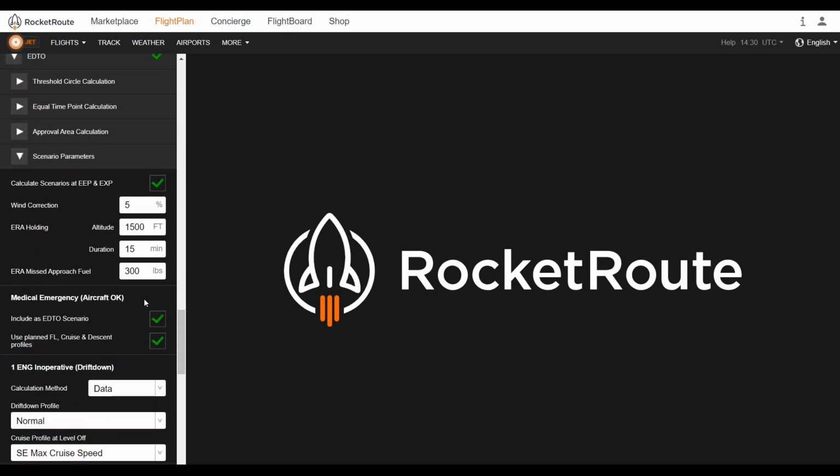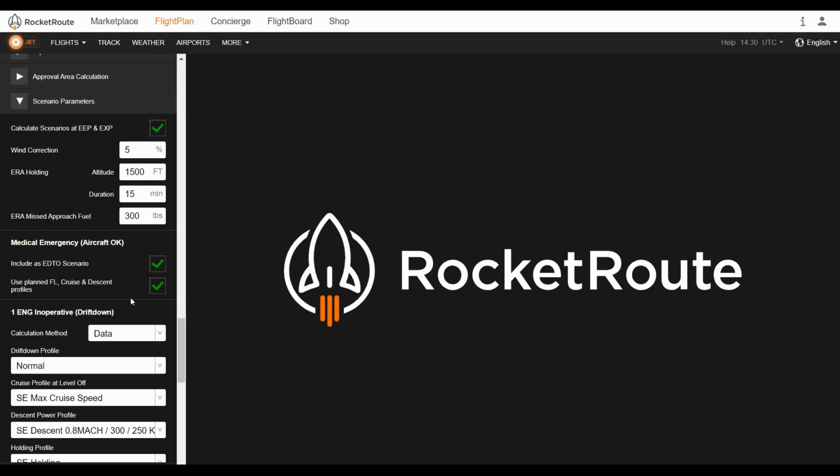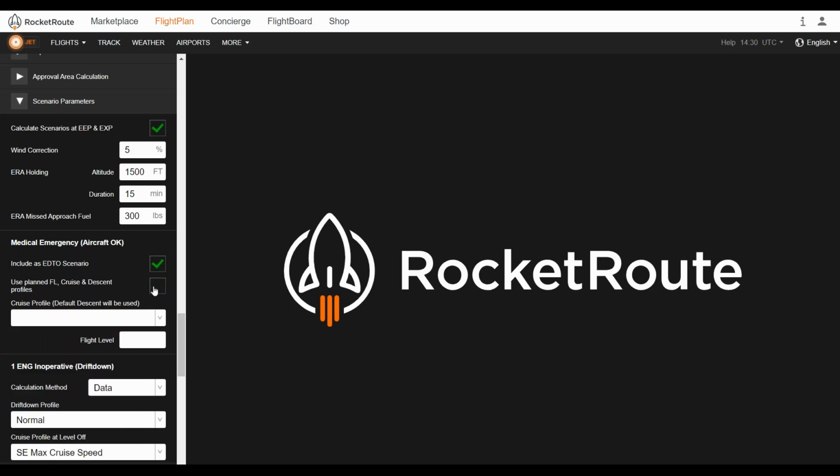Then moving next to the actual scenarios, the first one is the medical emergency. You have the option to either include it in the EDTO scenario, or omit it. The second setting is whether to use the flight level, the cruise profile, and descent profiles from the actual flight plan, or you can adjust the cruise profile and the flight level to your preferred ones for this type of emergency.